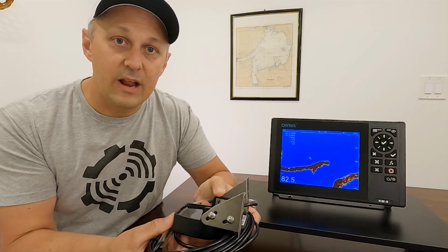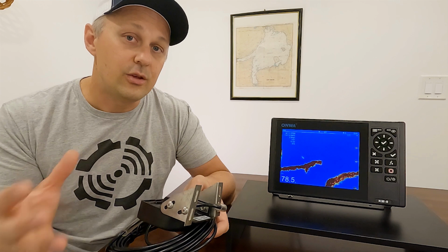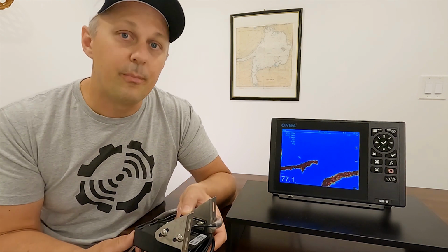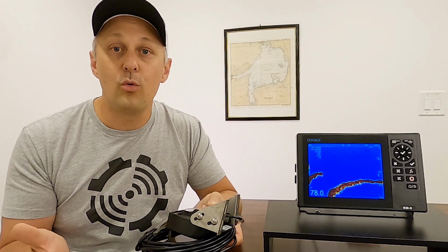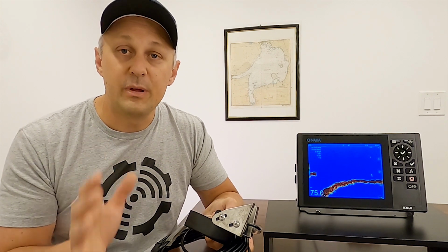So what is Sonar and what does it do for you? Well, like I mentioned, you'll get the depth and fish finding ability with it. So what it requires is you to mount a transducer on the boat, and there's various types of transducers depending on the type of boat you have, and it's typically determined by the engine setup. So if you have a boat with an outboard or inboard outboard, transom mount transducers would be perfect for that.